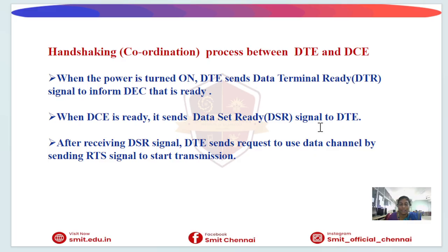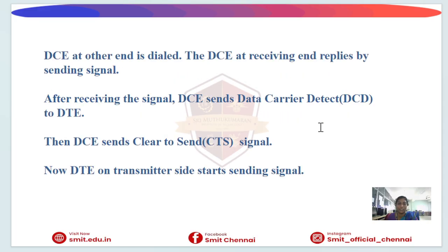So this coordination is handshaking. This we are seeing. Then the receiving DCE responds. What will the DCE respond with? The DCE sends the DCD signal. What is the DCD signal? The communication link is established. So no problem, you can send the data.